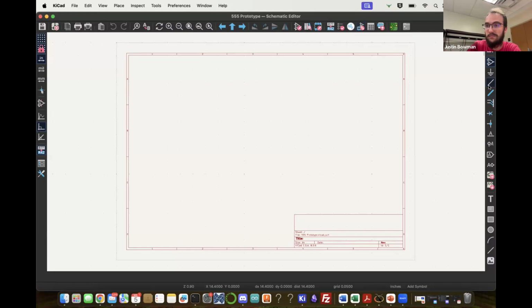On the right over here, we have our symbols. We have our power and grounds that we can have here, lines to connect different ports of our components, and some closures just so that the system knows that one pin is to be left floating or stuff like that. So that's what this X does. The rest isn't used too much. Some are for more housekeeping stuff, but we'll talk about that if it arises.